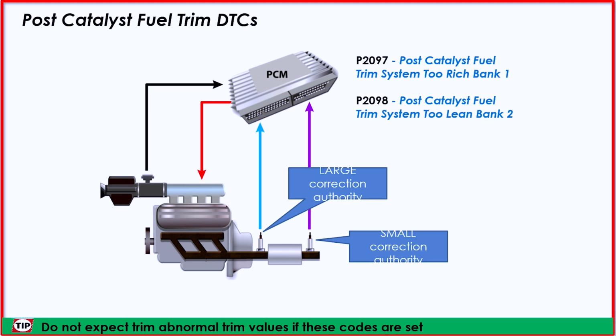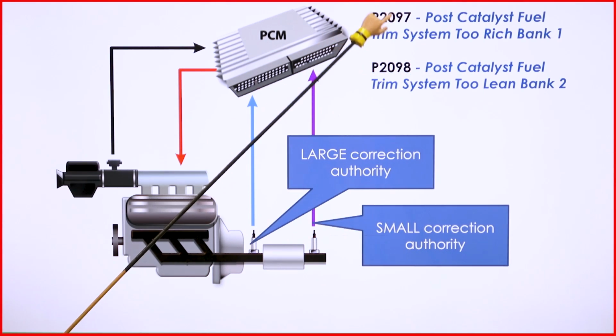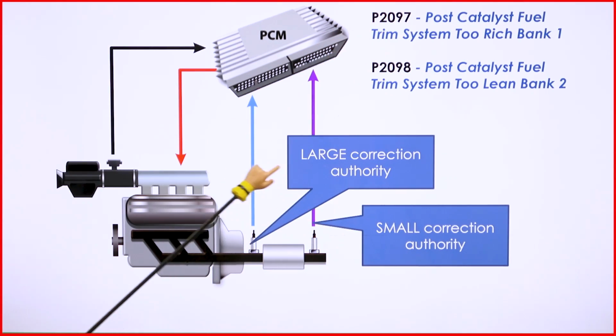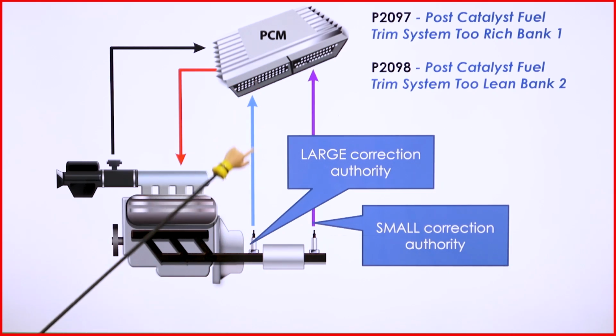Additionally, on newer vehicles, we're seeing post-catalyst oxygen sensors being used to trim the fuel strategy here. And there are 2 predominant trouble codes set for those. It's very rare. Quite often, most of the trimming is happening off the front O2s or air fuel sensors here. But I just wanted to acknowledge that there is some correction or fine tuning happening by using these rear O2 sensors.